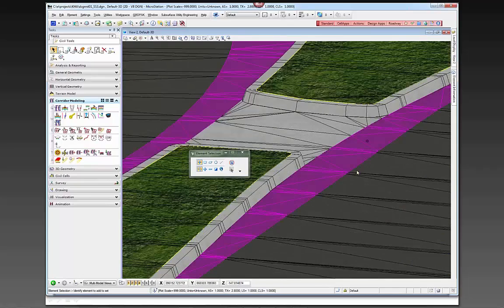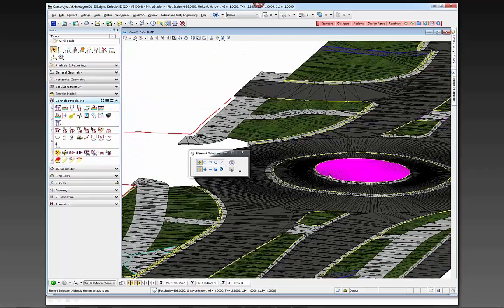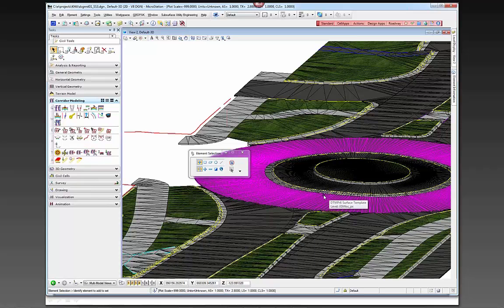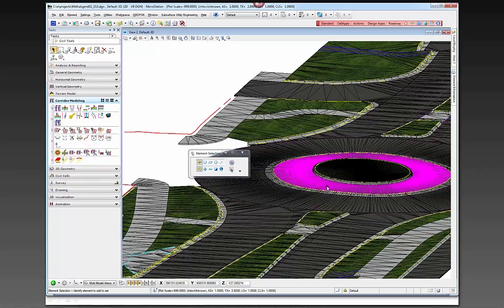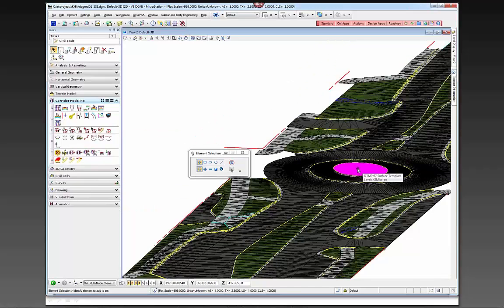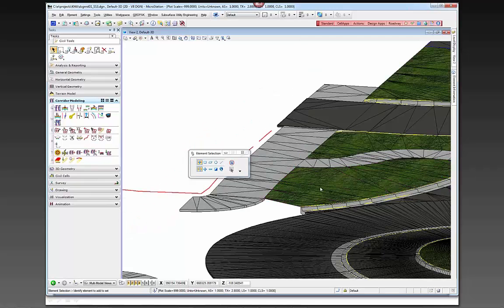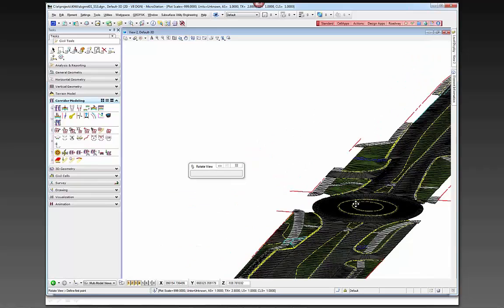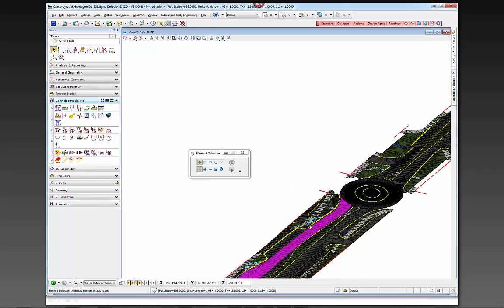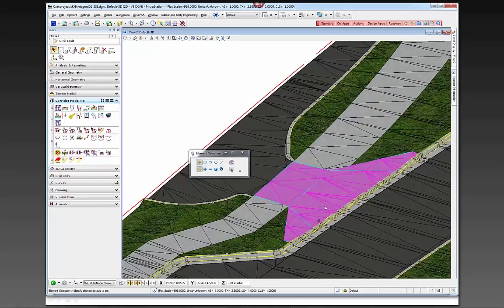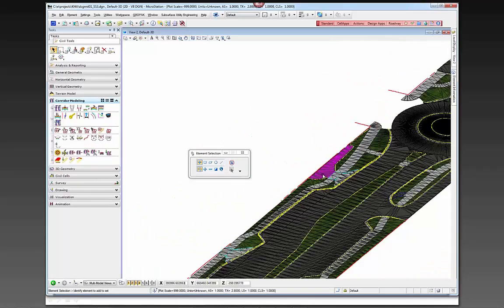This is a pretty simple linear template. It can go along a profile on this inside edge of pavement, then have a slope line out, and then build everything back into the middle there. Then you have all the sidewalk back here, and it's just a matter of building terrains in between the boundaries based on the 3D profiles of all the rest of them. So it's definitely achievable. You can get really good. This is a sample of the 3D driveway and parking lots back here with a parking lot curb.